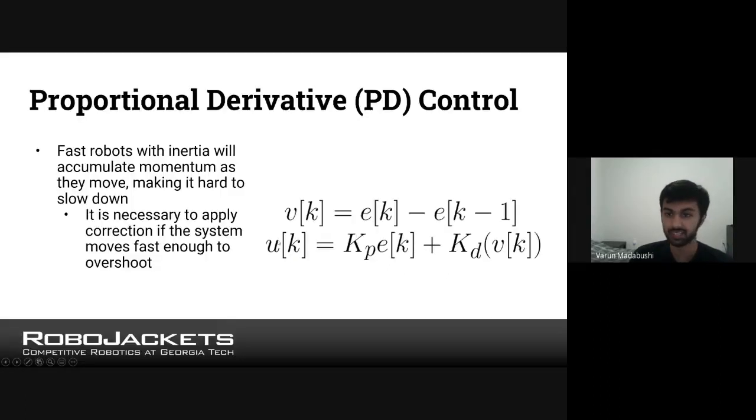So you can combine P, PI, PID, PD, any combination of those. Generally, you want to have proportional control, but you can add integral or derivative control as you want. The integral term, like I mentioned, basically adds an extra inertia effect, and the derivative adds an extra damping effect. So integral adds energy and derivative removes energy.